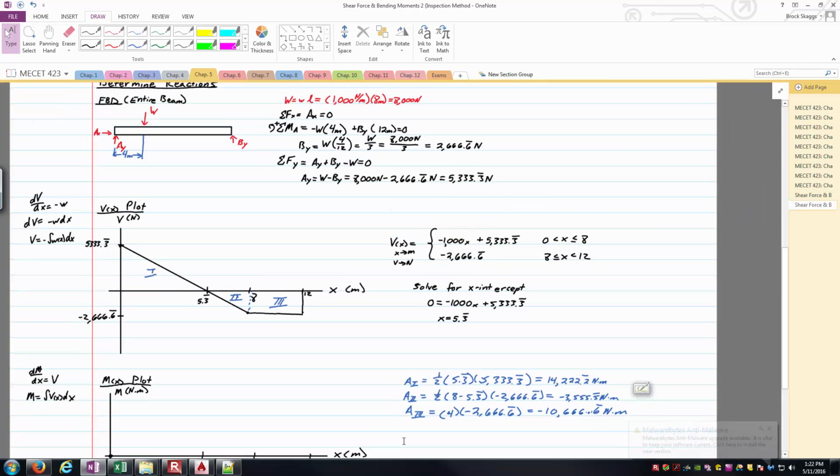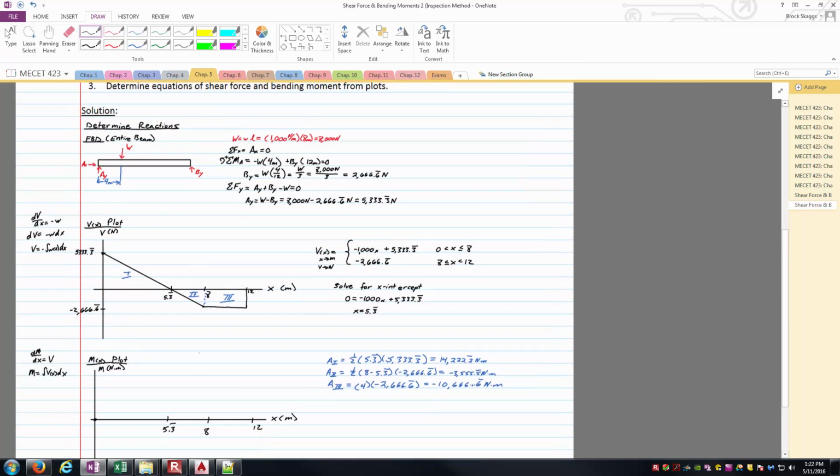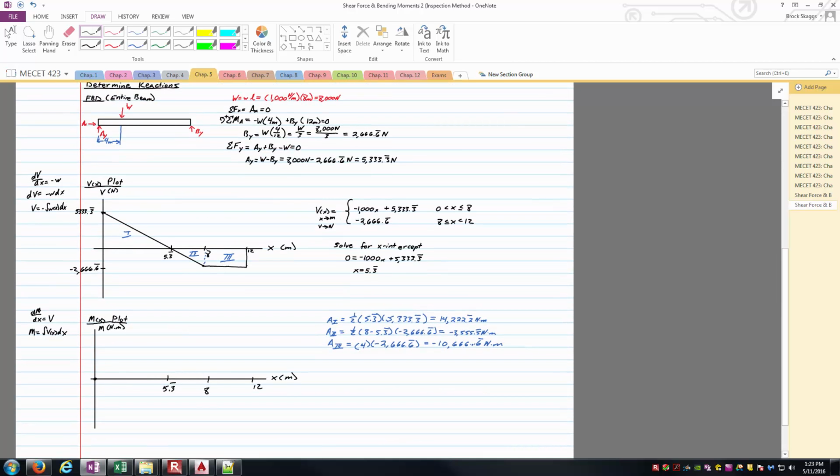And so what we've basically done is determined the amount that the bending moment is going to change between different x points. One of the things to take note of is that there's no externally applied moments, either reaction moments or moments that would come from externally applied loads on this beam itself here. And so one nice thing about that is I should be able to sum these areas up, and they should sum very close to 0. Maybe some rounding a little bit with just the way the calculator is working, which is basically what mine's saying. I get negative 1 times 10 to the negative 9th values, but essentially think of that as 0.